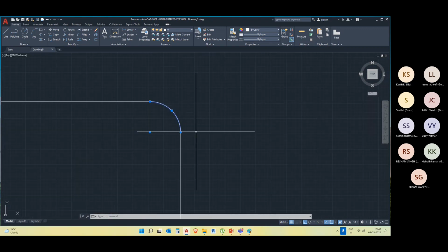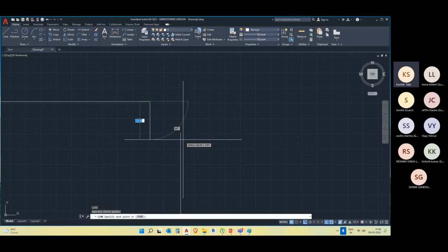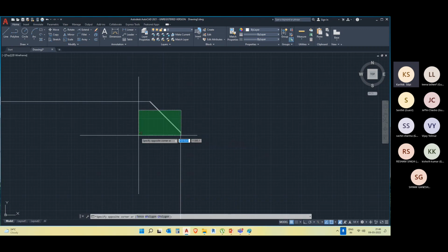But having a fillet is difficult because it takes a lot of manufacturing steps. So in less complex areas, instead of machining it and giving it an angle, which is a difficult process, what they do is they'll just cut the parts which are not important, the parts that don't have a human interface. They'll just cut this part. That is called a chamfer.